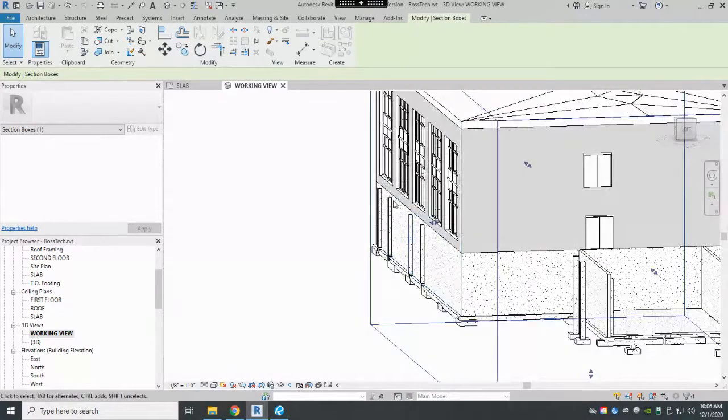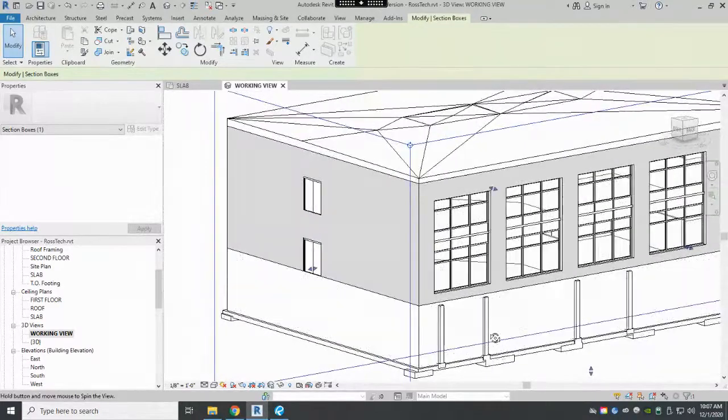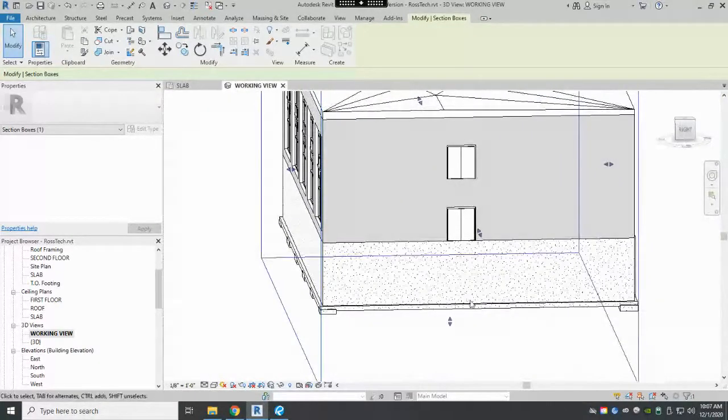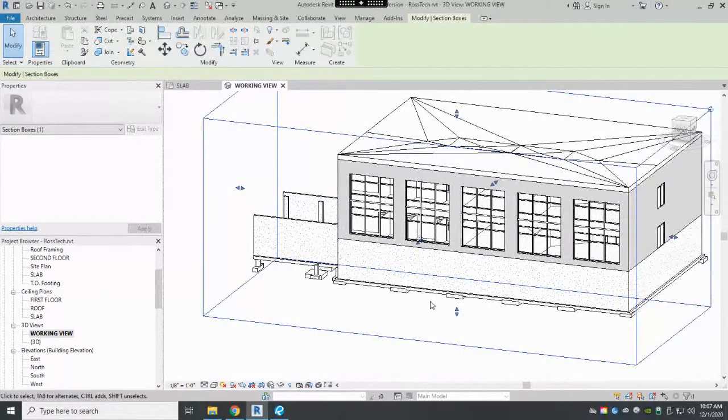And the heights of these columns that we see here on the edge, on the outside, and where they are located all have to do with the column grid and the datum that's being used for measuring the elevations of all these things, which is going to be the slab level in the basement.